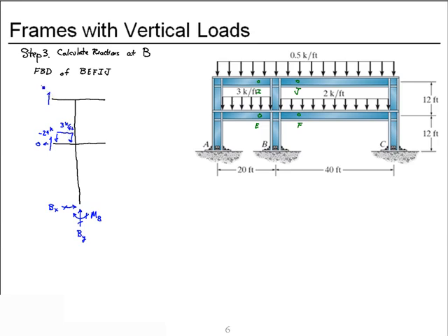shear at point I of minus 4 kips, the normal of 0, and this entire top beam segment has a distributed load of 0.5 kips per linear foot. The shear at J is positive 8 kips. The normal at J was 0. Shear at F, positive 32 kips. The normal at F, 0. And the distributed load over this segment of 2 kips per foot. The dimensions are 4 feet on this side, 2 feet on the left side.